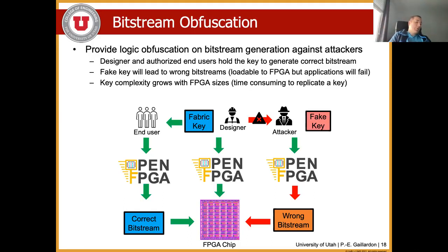So obviously that concept does not really apply to very large productions of FPGAs. But if you think about DoD-based eFPGA production and stuff like that, that makes a lot of sense, right? So you can really protect a small fabric against some attackers. And the secured bit stream is done entirely, again, as part of the open source tooling.